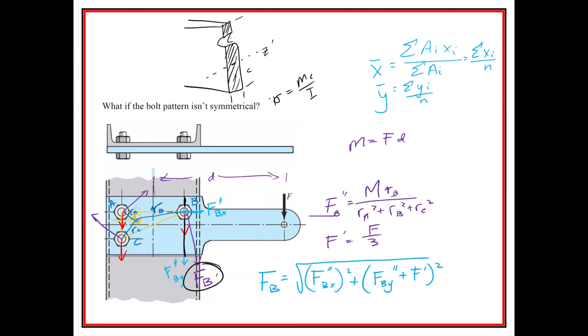So the centroid, if this is going to be the diameter right here, and let's call this the width right here, and of course that's the thickness right along here of the thing. We would have I equal to, let me see, I'll just write the thing out, BH cubed over 12. So it's TW cubed over 12, but now we have to subtract out the distance we're going to move it. The Y distance, I'll take it from this baseline right here. That Y distance to the baseline is going to be W times T, right? That's the area, times W over 2.